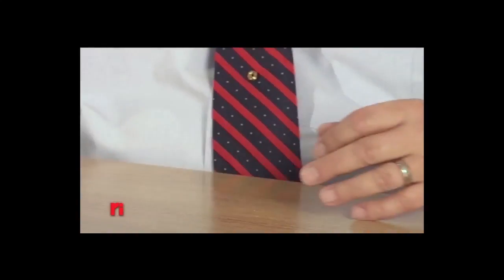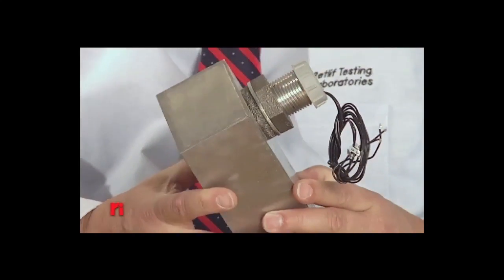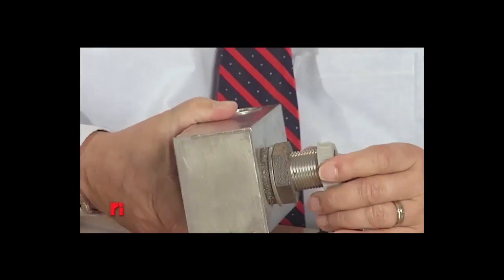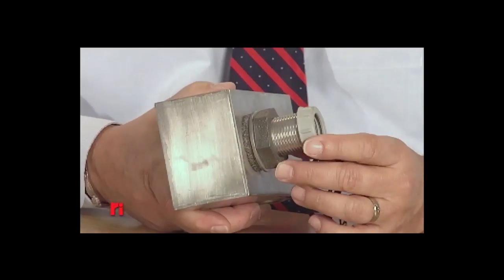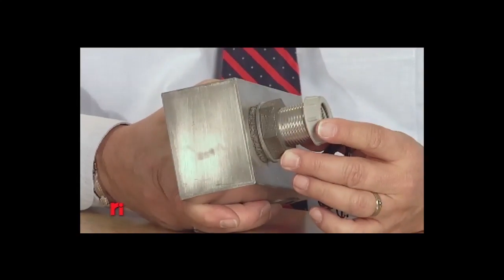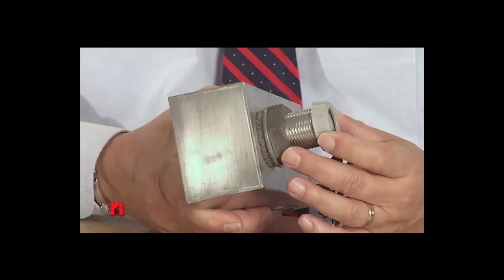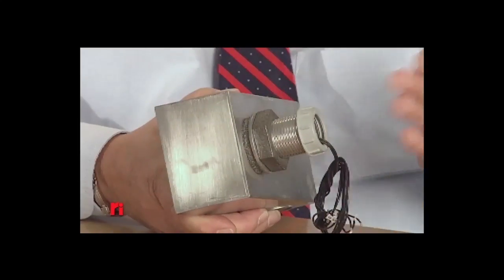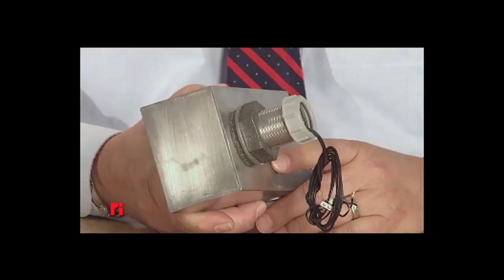Here is another example of a mil standard type filter. This is a small power line filter, but again you can see it has this rather large threaded neck on it that would penetrate the hole in the enclosure or in the cabinet, and that when properly mounted then provides that metallic isolation between the input leads and the output leads of the filter.